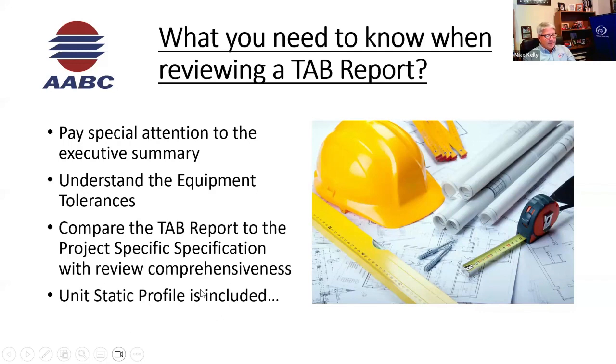It's such an easy task that doesn't get done: a static profile sketch to show you pressure losses throughout the equipment, filters, coils, air handling fan, discharge air, filters, reheat coils, whatever it may be. That should be in there. So that's my little thing I threw in here.